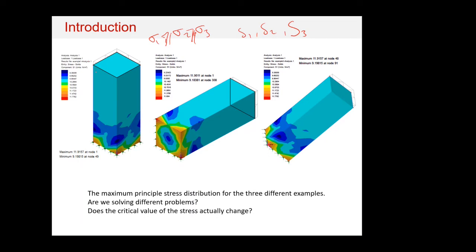And if you look into sigma 1, for the first case, when we have the axis parallel to the z direction, you'd see that sigma 1 is again exactly the same range, running between 11.9 to 9.1. If you look into this case, this is 11.9, 9.1. If you look into the third case, this is 11.9, 9.1. So if you calculate the principal stresses, you would always get the maximum possible stress, and the maximum possible stress is going to work for you.